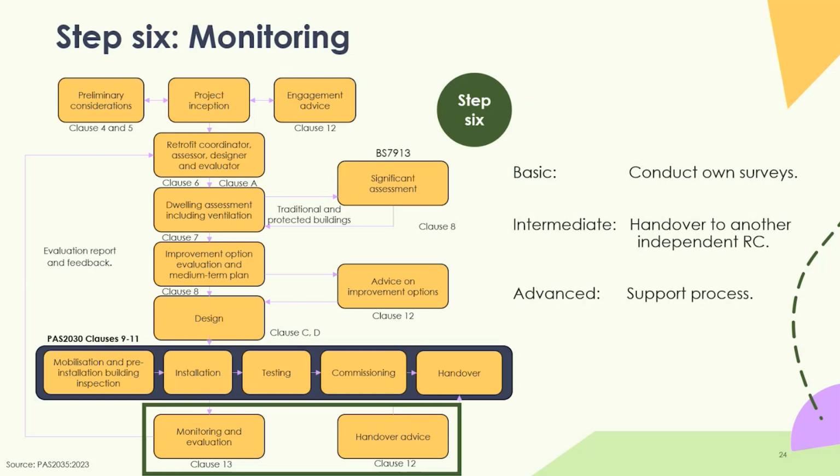Ventilation is particularly important because generally when you've done a retrofit, you might well put in some sort of continuous ventilation. So a system or different individual room devices which run continually on a background level, and then when moisture levels, humidity levels, or carbon dioxide levels rise to a certain amount, they will go onto a boost setting. So they'll come on as a normal extractor fan in a bathroom or kitchen would when you switch the light on. But once that level has dropped, they go back down to a background level. And as they're working on that background level, on a low tick over, as it were, it's not uncommon for residents to think that there's something wrong, that those ventilation systems shouldn't be on all the time, or that they're using energy that they can't afford. It's a very common thing. They use very, very little energy, but they are essential to avoid damp and mould developing.